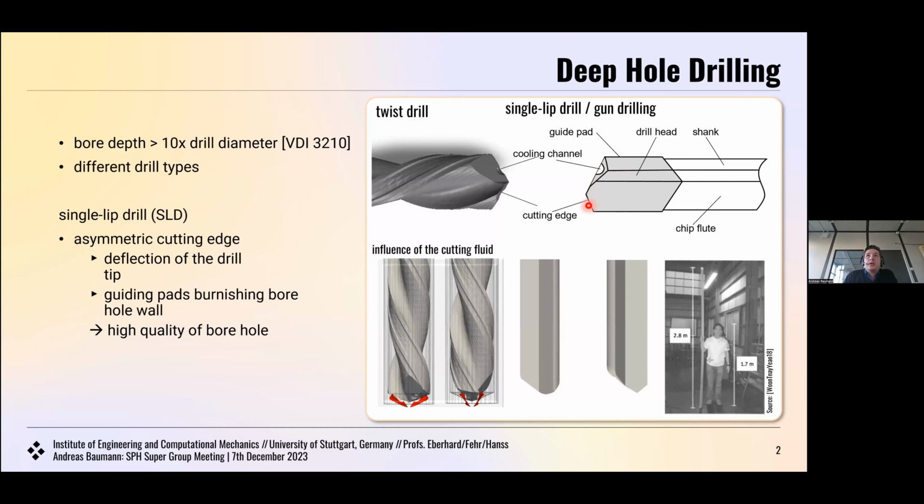Furthermore, due to its features, it has a high straightness of the borehole, and it requires this cooling liquid way more than a twisted drill. We don't have any helical flute which would already remove the chips from the borehole, and thereby we are completely relying on the cutting fluid.